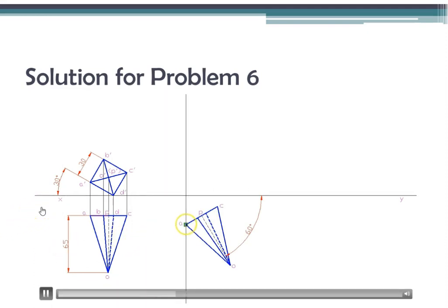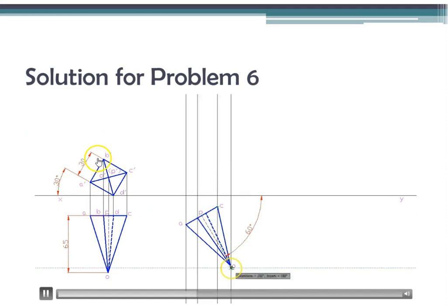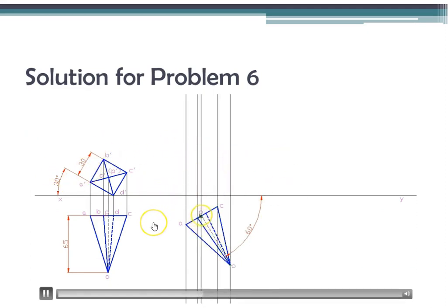So the axis is inclined at 60 degrees to the VP, and you project upwards towards the front view above the XY line, and from the old front view, project back and get the final projection. You could see that one thing you could imagine now is the base, since it is away, the base will be hidden from view in the front view.